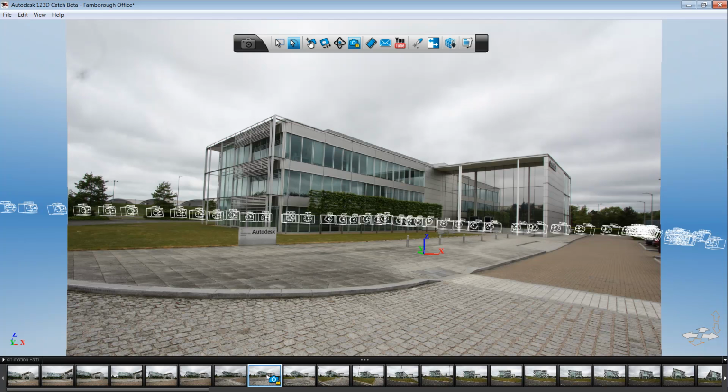Okay, so now what we want to do is really use these photographs to help create a three-dimensional space. This is ultimately going to help us create the energy analysis model. And there are two strategies we can employ when looking at a building. The first is to trace vertically up and down each face of the building. The second is to trace around the plan of the building, and that would be my preference for this particular building type. With the plan traced, what we can then do is extrude it within the Revit environment.